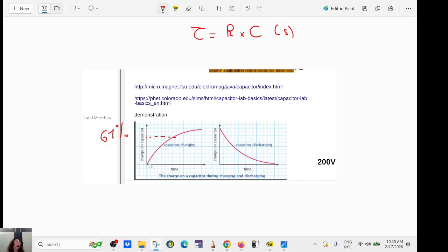First it's very easy to charge it because you have a plus. Okay, plus is fine. And then another plus. Two pluses, they don't like each other, but they are fine. But as you put more and more pluses, they start to really hate each other. It's crowded over there. So it takes more work to reach the voltage, to charge a capacitor to your voltage.